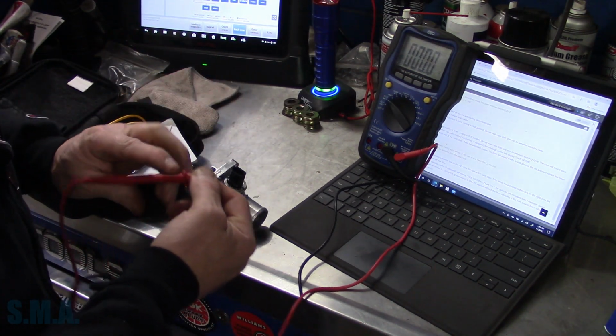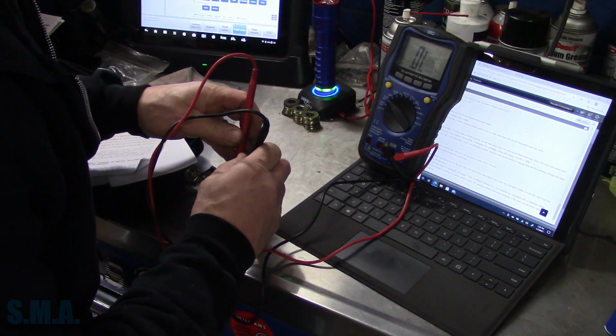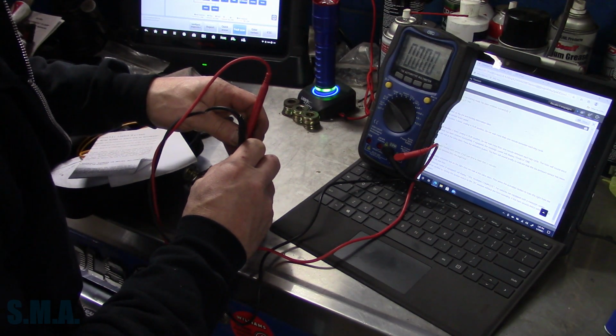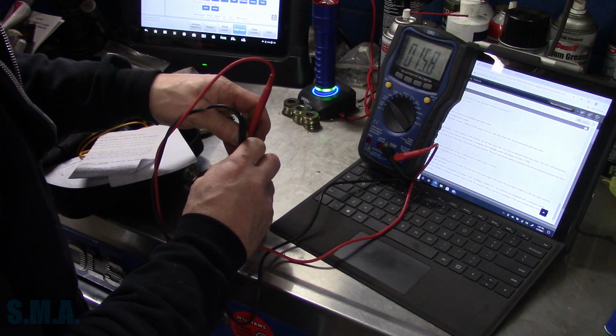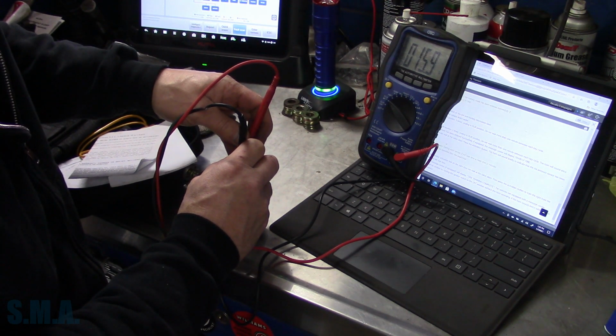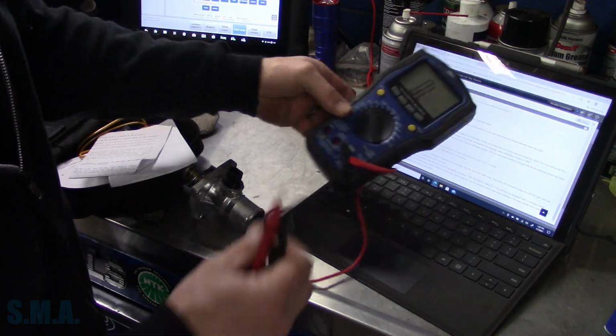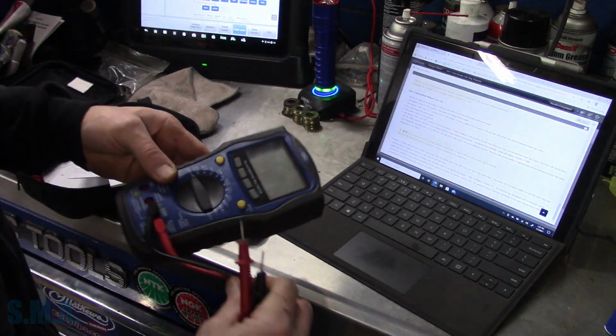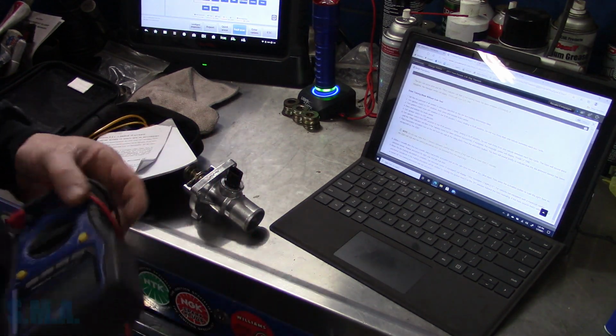Yeah. Okay, our leads are good. A known good is 15.7 ohms, or 15.8 ohms, or 16, I guess it's settling around. About 16 ohms, we'll call it, is a known good. So if you're checking yours, just a test light and an ohm meter, and you should be good to go.